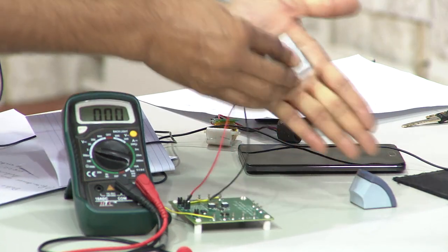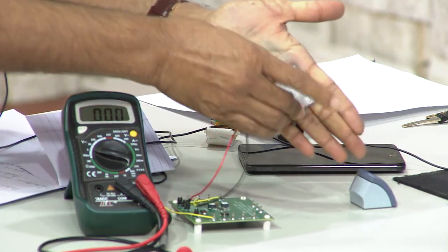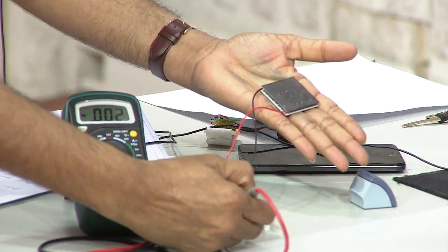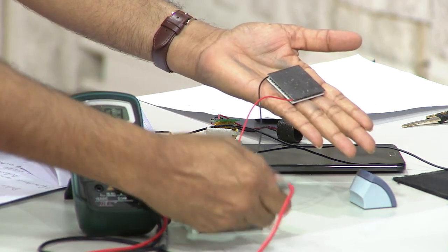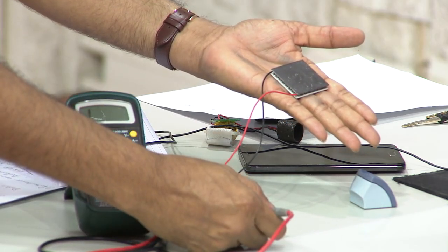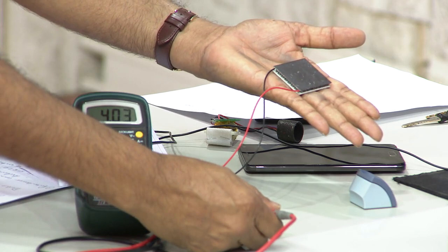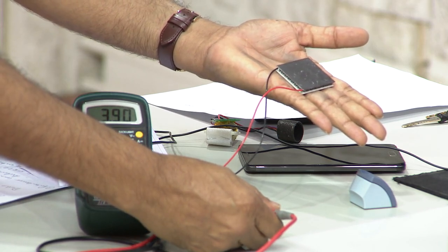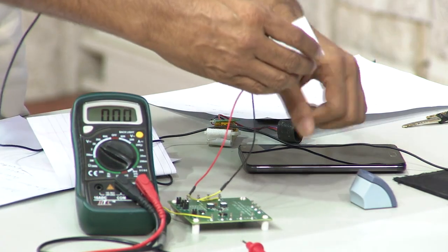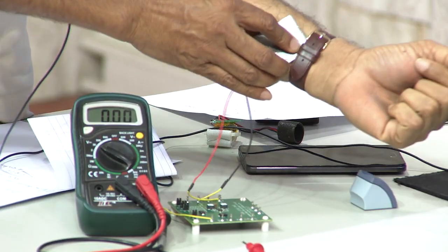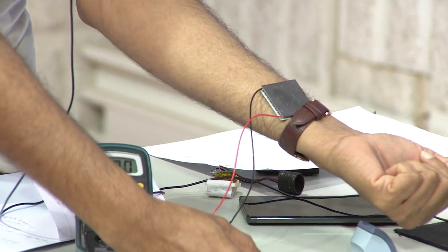so that I heat this side and let us see another measurement. You can see it has gone a little over range. Yeah, you see it has developed up to 4 volts, which is a clear indicator that if the temperature differential exists, you can actually harvest from this device.